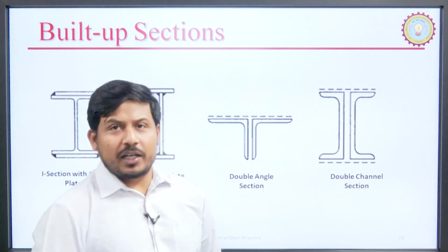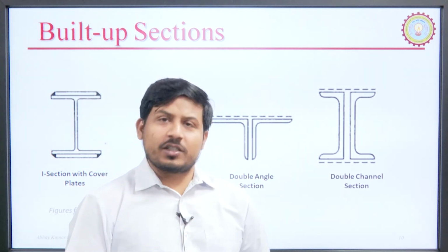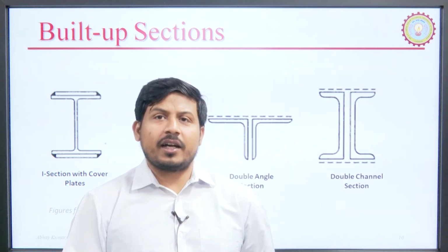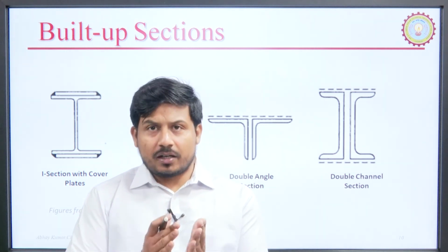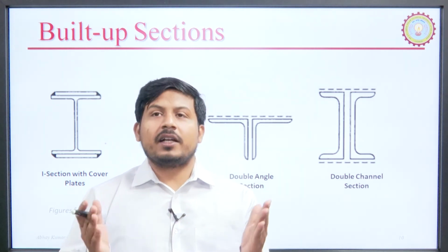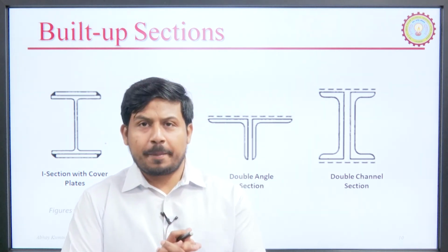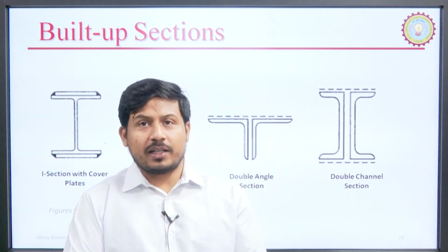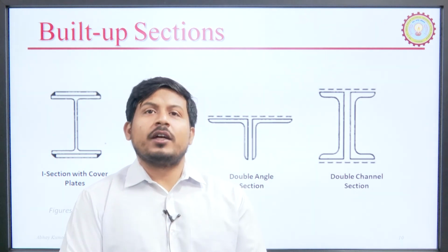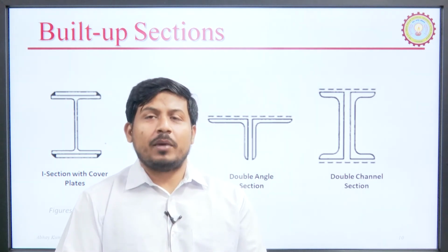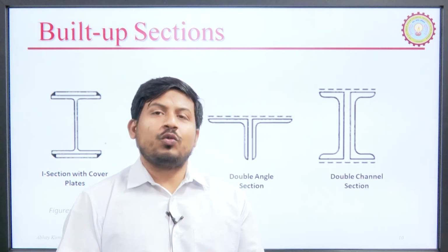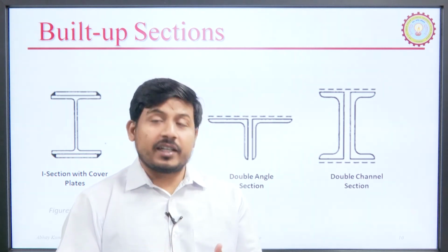Now, let us talk about the built up section. What is a built up section? As its name indicates, this section is built up. It means it is a combination of two different sections already available in the market. Why do we need to make a built up section? We need a built up section to increase the capacity of the member.